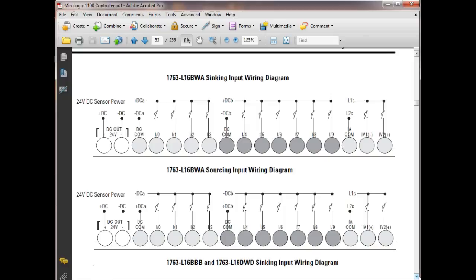If you take digital logic, we talk about sinking and sourcing all the time. But as sinking, we use the minus as common. Sourcing, we use the plus as common. So notice all my switches up there have a common. Common is just a point that we use to connect everything to, right? You understand? Right. And they're connected to positive. So I have my input, the device itself sourcing, and I have my input sinking. Y'all understand that? People get confused about that.